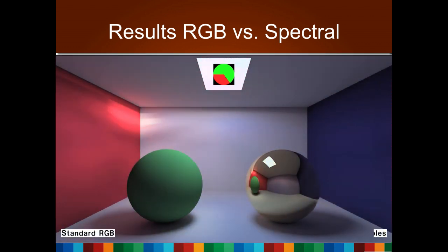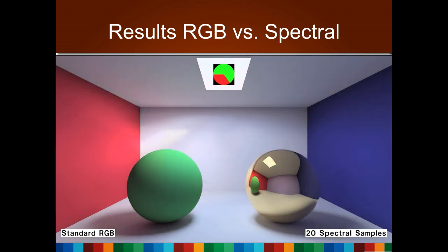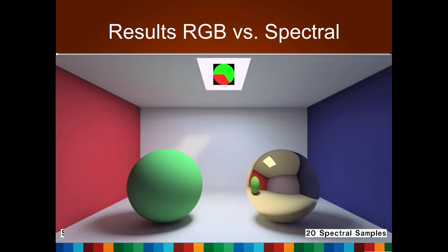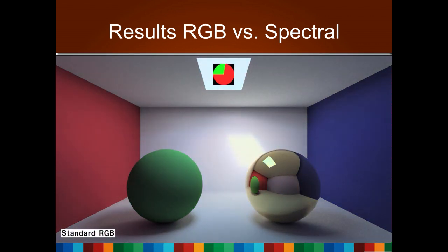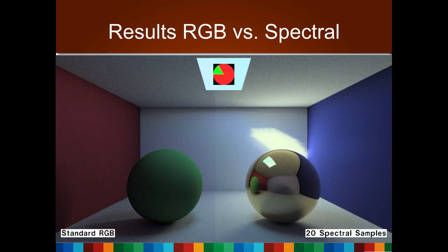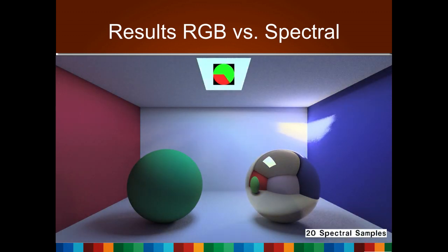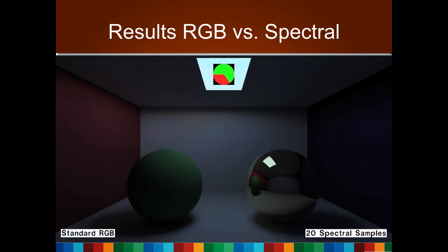So this is a kind of a fun animation. This shows what the transmittance is. So the maximum transmittance is 80% or something like that, 60%. So that's showing 60% transmittance. And sometimes of the day, it goes down, and that's where it's trying to block some of the light and decrease the transmittance. So you'll see that happening in the afternoon in particular. And this line going back and forth is showing the difference between a full spectral calculation and a standard RGB calculation. It's a busy animation.